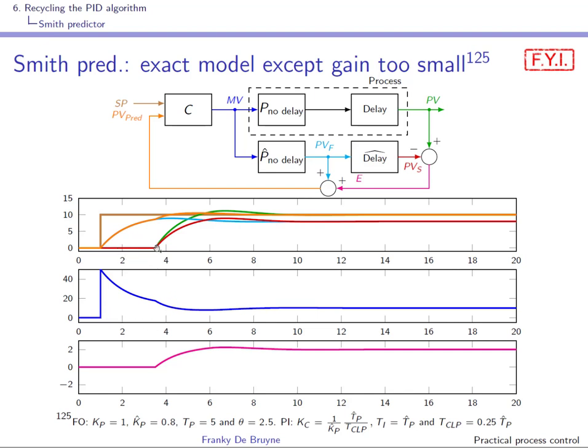And this is seen after the period of the delay, because you can see that the value of PV is higher than the value of the model. So there is a positive error, and this positive error is added on the fast PV, right? We see now a difference between the fast PV and the predicted PV.